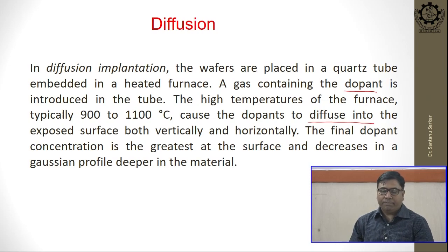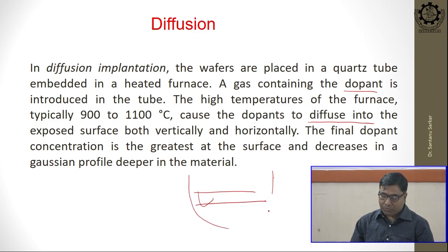So, in this case of diffusion, what is happening? You have the wafer and you are putting it in a quartz tube, and your gas is flown at a certain temperature and pressure, and it will diffuse into the open region. Okay. The region you do not want to diffuse into will be coated, okay, hardened coated.